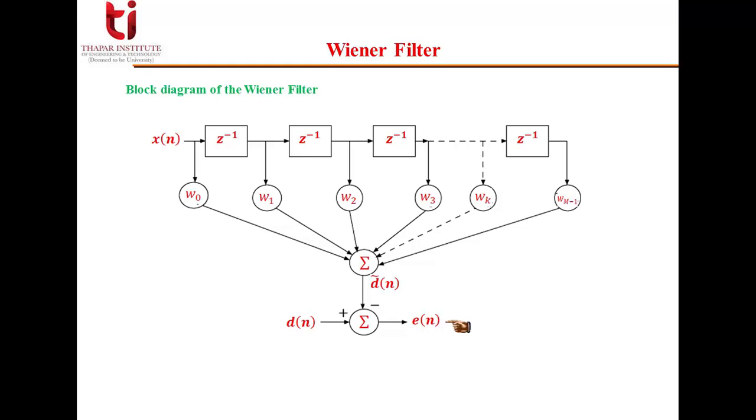Now if our designed filter is an optimum filter, this error should be minimum. For that, we can say that this en, which is the difference between the desired and the estimated signal, is the optimality condition we want to achieve. Basically, we are not taking this estimation error as such. We are taking the mean square error of this.